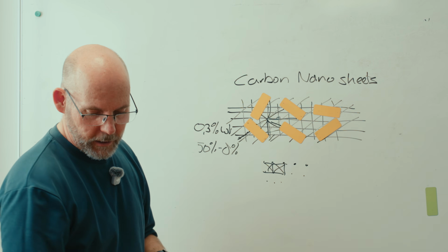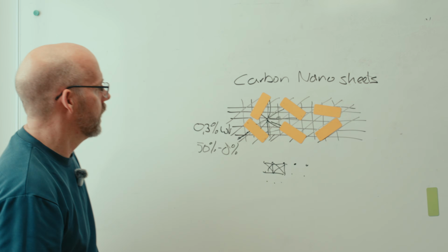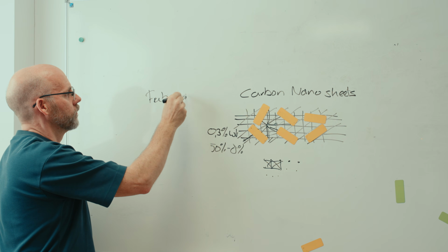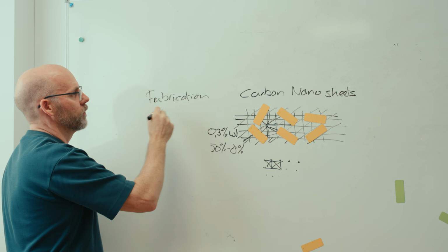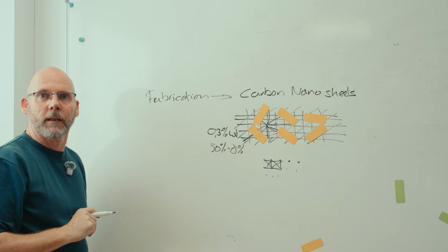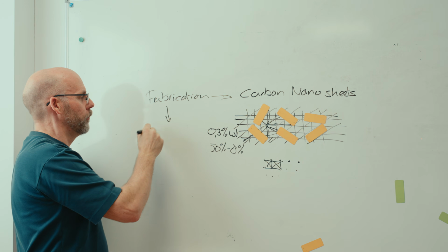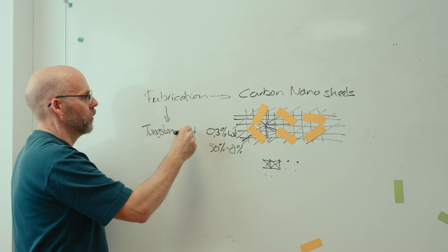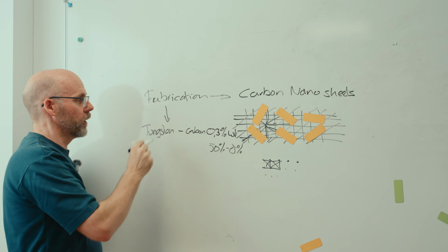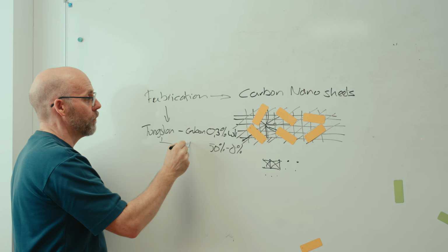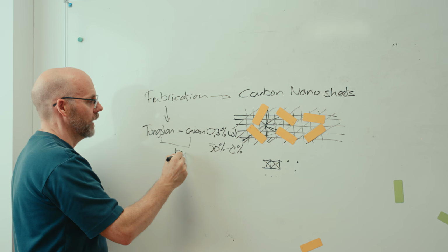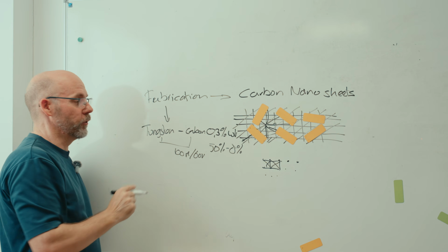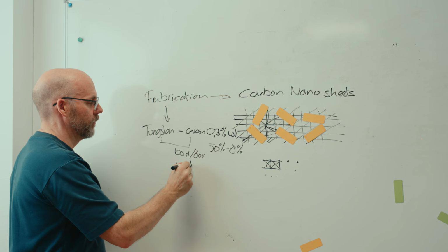What we're currently in the process of, we're planning our own fabrication of carbon nanosheets. And we're doing that by using a tungsten and a carbon rod under high voltage, high amperage. So think about 100 amps at 60 volts, creating an arc between those two in a water bath.